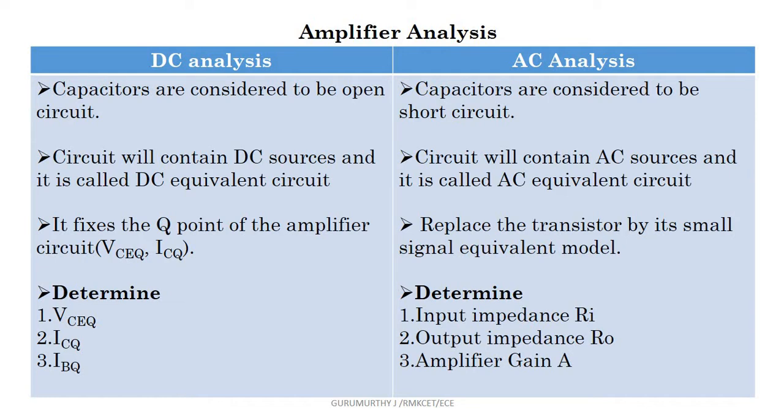Why? Because the reactance of the capacitor is 1 by 2 pi F C. In DC, the frequency F is 0. So when F becomes 0, reactance becomes infinity. Infinity is nothing but open circuit.